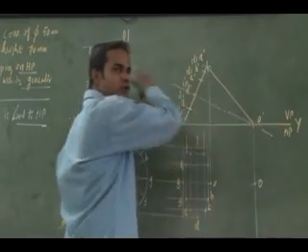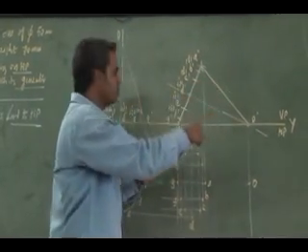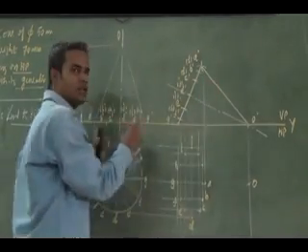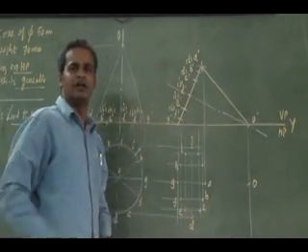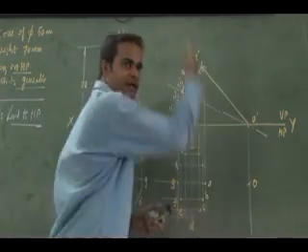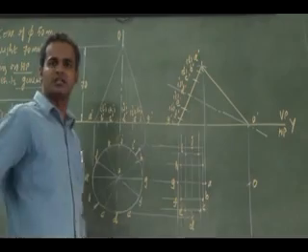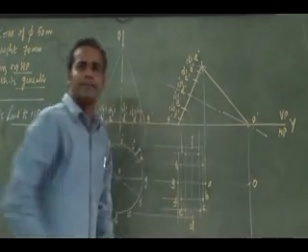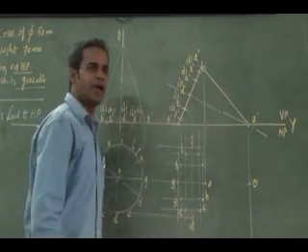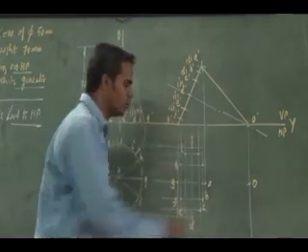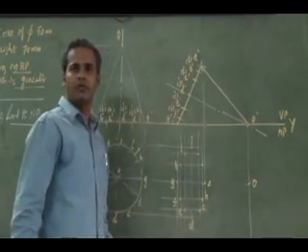Then I have reproduced the previous front view, and I have marked all the base points at the appropriate locations. Then I have projected from the final front view, and I have extended projectors from the previous top view, and I have got all my base circle points, circumference points in my top view as well as the apex in my top view.